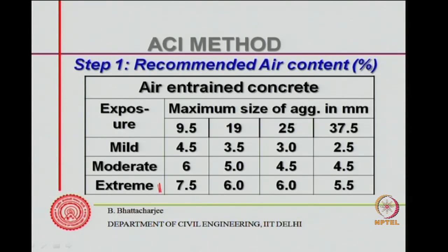For extreme exposure condition, this air entrainment should be 7.5 to 5.5 depending upon MSA, and for mild exposure it is 4.5 to 2.5.